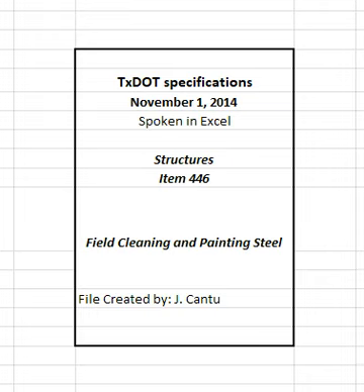Do not apply paint to any surface with discernible moisture. Do not apply paint to any surface when steel is within 5 degrees Fahrenheit of the dew point. Do not apply any paint when impending weather conditions might result in injury to fresh paint. Provide environmental controls such as dehumidification, heaters, or additional containment measures as needed to control and maintain favorable atmospheric conditions in all areas of the containment. Provide environmental controls at no additional cost to the department.